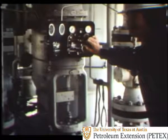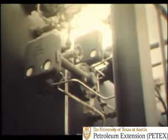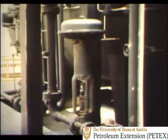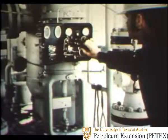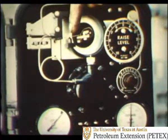Then we looked at the back pressure control required to maintain a constant pressure on the separator, and the liquid level control to maintain a proper operating level in the vessel. Then we looked at the main components of the back pressure and liquid level control loops, those being the controller and the control valve. Inside the controller, we saw the adjustment knob for raising or lowering the pressure or liquid level, and the flapper and nozzle that controls the output air to the control valve.